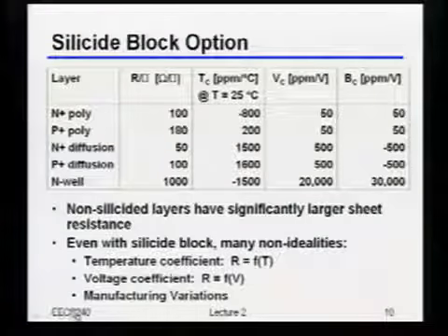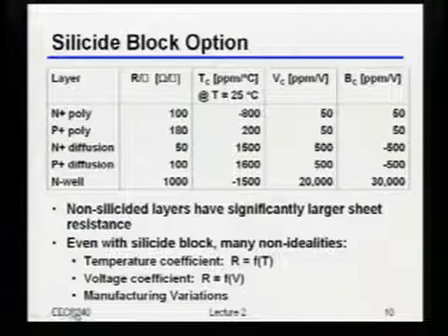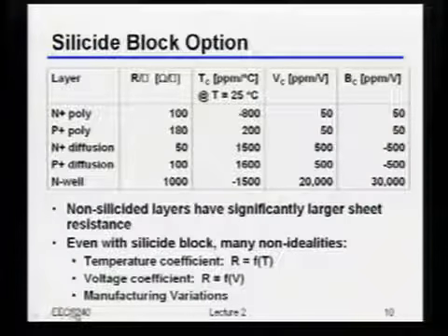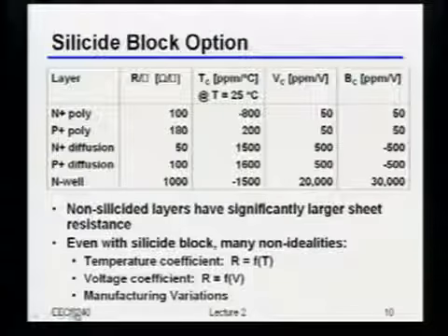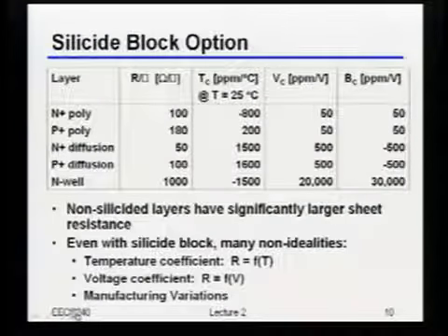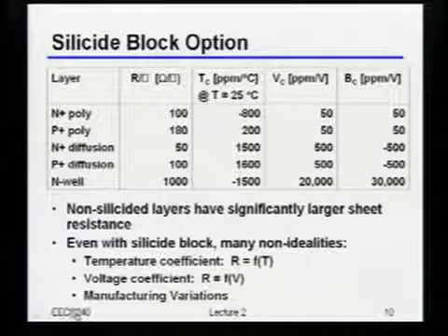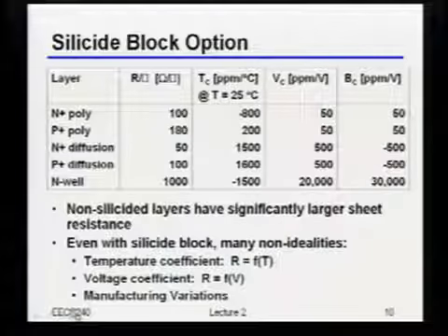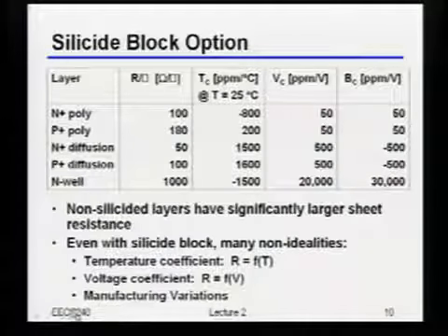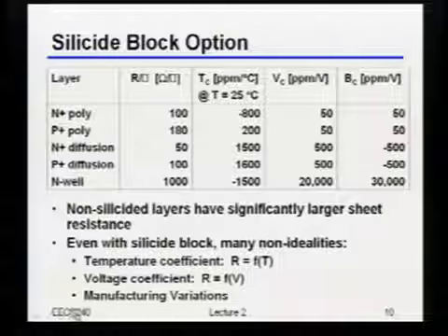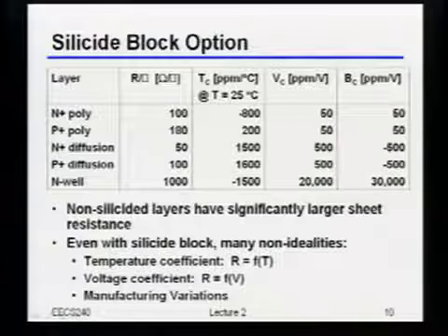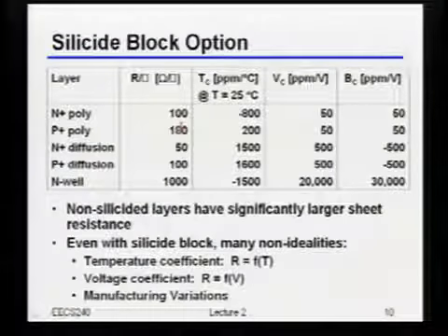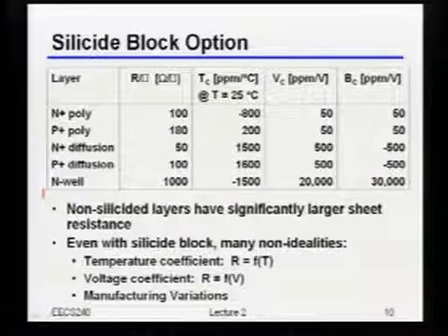Well, the one good news is that it's fairly common these days that you get the so-called silicide block option. So that just means that rather than them applying the silicide to whatever layers they usually do, which is usually polysilicon and the diffusions, you can just tell them, okay, don't put any silicide there. And if you do that, you'll get substantially higher resistance. Because again, the whole point of putting the silicide was just to drop the resistance. So if you do that, you can again get reasonable ohm per square types of numbers. So somewhere in the, let's say, 100 to maybe a couple hundred ohms per square. So not quite as good as that NWell, but still reasonable.